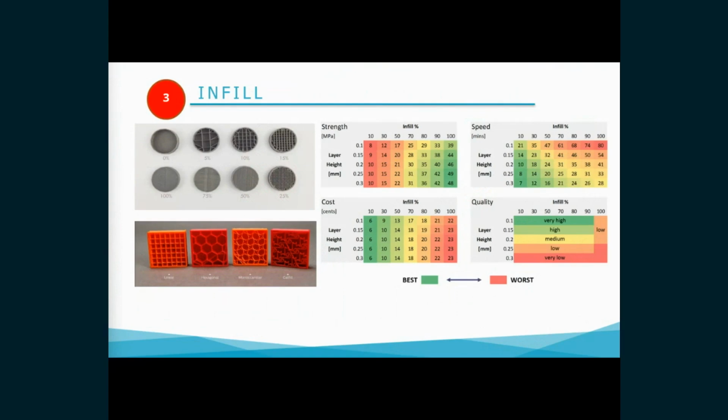For most standard prints that don't have to be strong or super strong, it is recommended to use an infill density of 15 to 50%. The density percentage keeps print time low, conserves your material, and provides good strength. Functional prints must be strong, therefore, it is recommended to use a higher infill over 50%. The setting is extremely high, so the print time will be longer and it consumes more material.